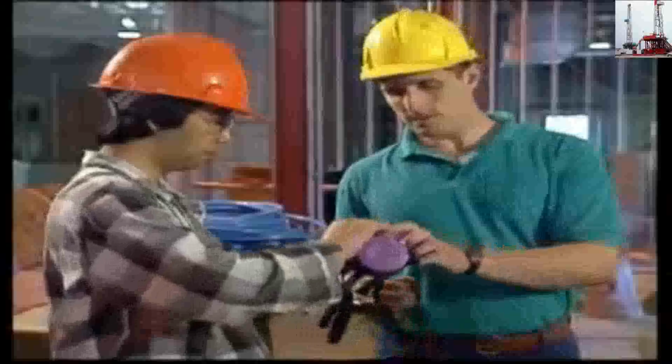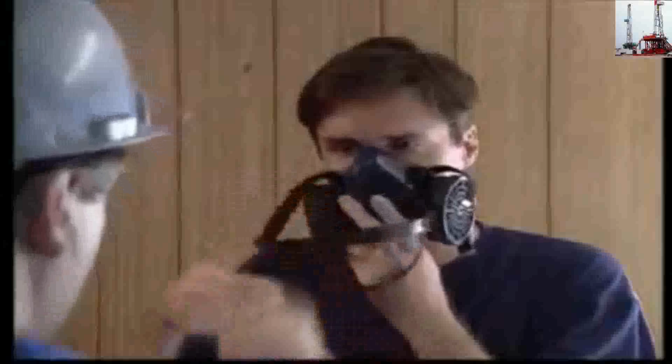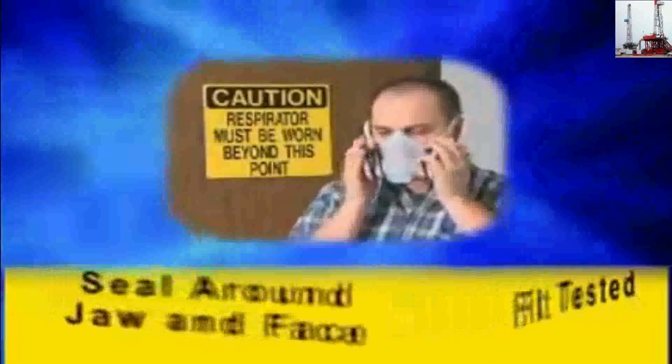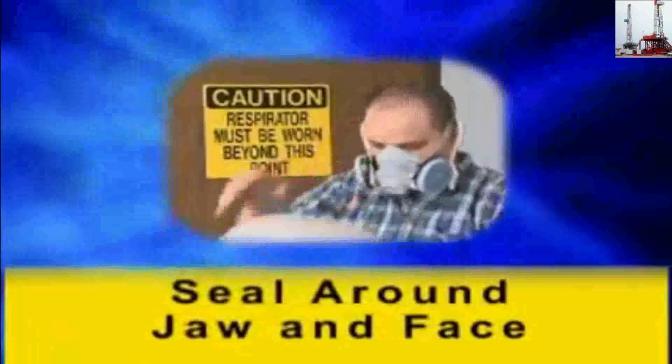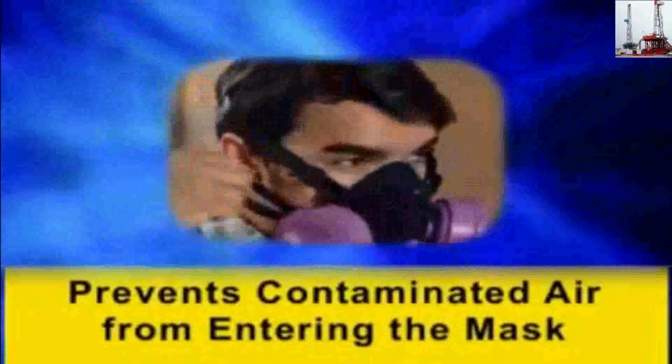An employer must provide training on the respirator and have a satisfactory respiratory program as required by OSHA. This program includes fit testing and medically qualifying all employees before they ever use a respirator. Before each use, respirators should be fit tested. The facepiece should seal around the jaw and face. Any facial hair that prevents a tight seal must be shaved. A tight seal prevents contaminated air from entering the mask and being inhaled by the employee.